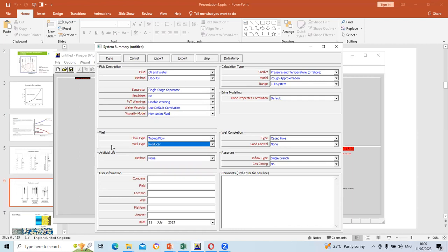That means they have done analysis and realized that the reservoir is at a good capacity, but there is no production taking place. It may be that within the tubing or the borehole, there is not enough energy to push the hydrocarbon to the surface. So they bring in an artificial lift method that will help to propel the hydrocarbon from the bottom of the wellbore right to the surface.